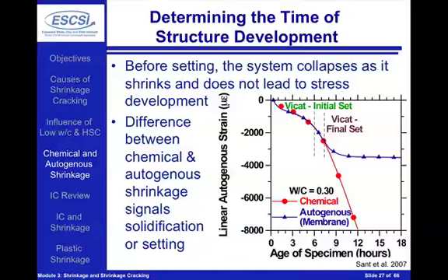They can't continue to just keep collapsing, and all of a sudden now we're going to start to build up a capillary pressure inside the system. We're going to start to build up this under pressure in the fluid, and we're going to start to create these vapor-filled spaces that we were talking about before. So all of a sudden these pockets of vapor are going to start to expand, and that's really what's going to give rise to this concept of self-desiccation.